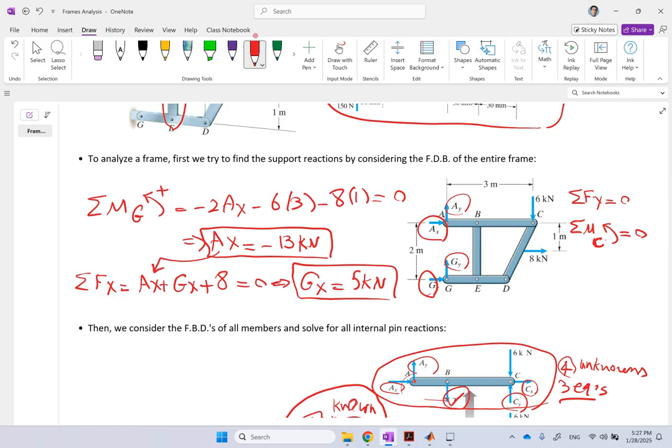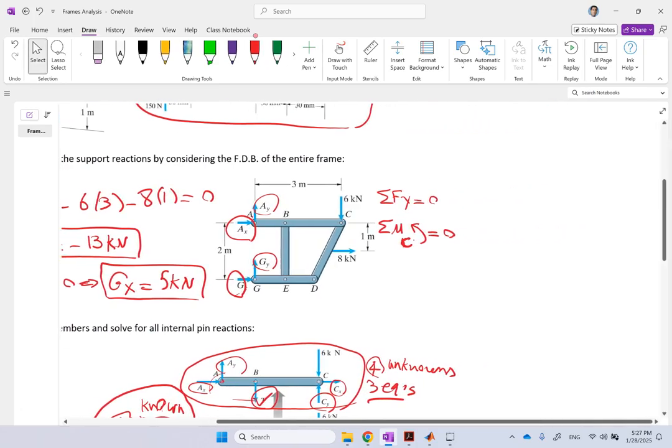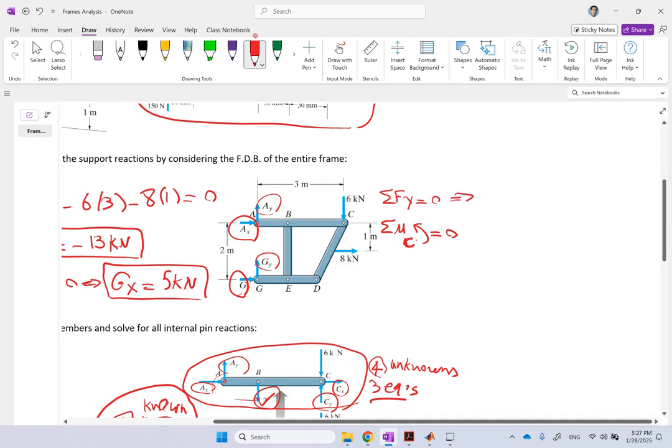These two equations will be the same. They are exactly going to be the same equation. Don't be tricked to assume that you can have 4 equations of equilibrium. You already used 2 of them. So you can only pick one of these. The next one is not going to give you a new equation. And if you don't believe me, just expand it, see what you get.